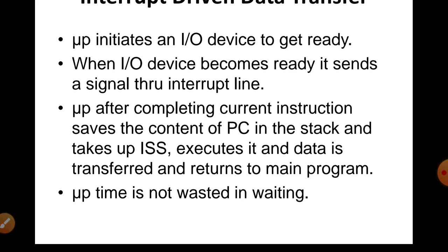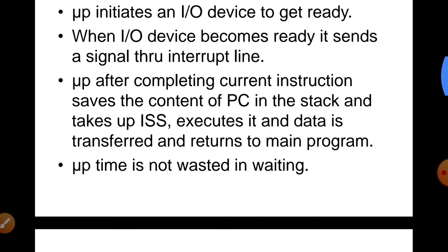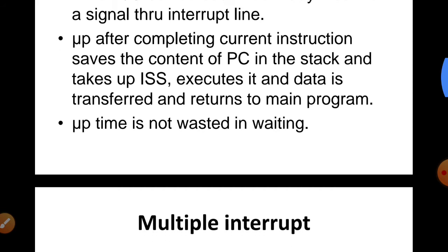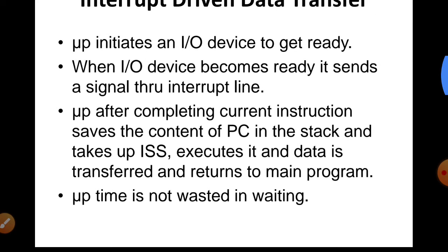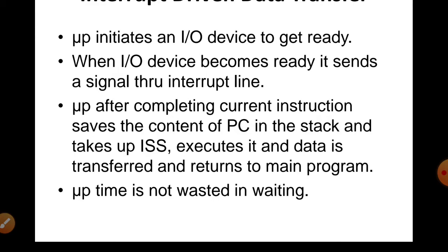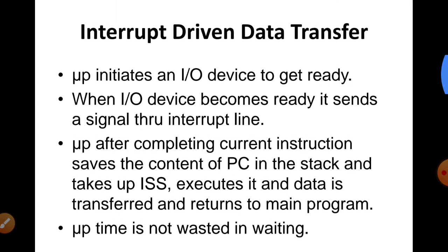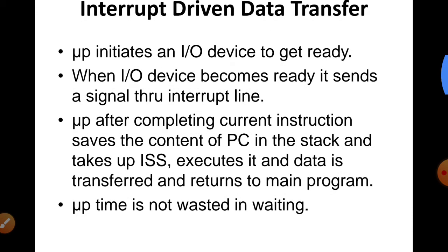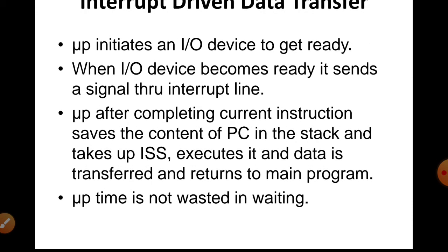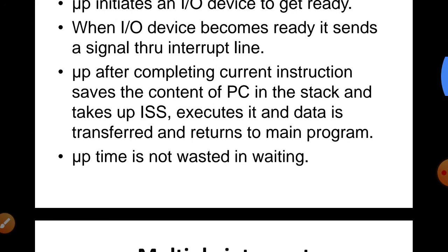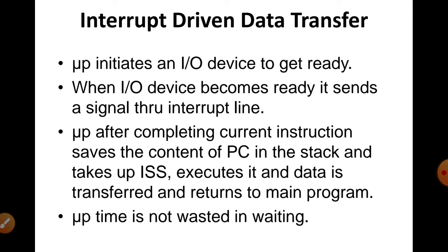Now this interrupt process allows the microprocessor to respond to an external request on a demand basis by executing the service routine. Whatever the microprocessor is doing, it will complete its current instruction, and then control will be switched to the subprogram meant for the actual data transfer.